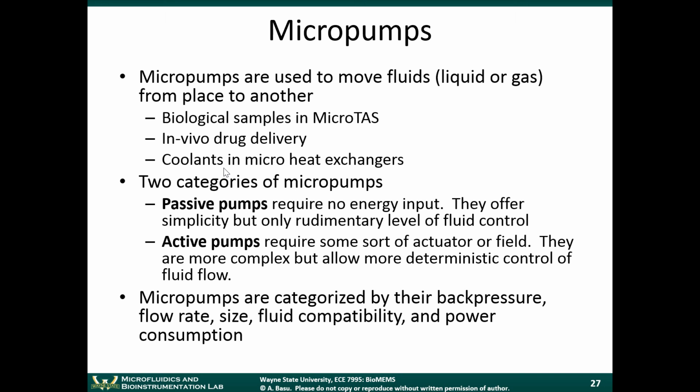An example of an active pump would be a piezoelectric pump. You actually have to drive that piezoelectric pump with an electrical source, right? An example of a passive pump would be a capillary pump, which just works on the basis of surface tension. So there's no external energy that you need to put into the pump. So we'll look at a few different examples of that.